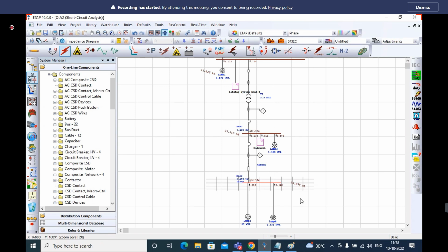Just check whether the option is enabled or disabled, and for which fault current we are getting the option. You need to know that. Here I'm running three-phase fault, so the fault current is displayed normally. Just select the grid and then right click. Can you see here, the Update Fault kiloamps option is there, but it is disabled. For three-phase fault, we cannot update from this design. Manually only we can assign. After running the design, you can check the fault current, and that fault current you need to assign in the earthing.